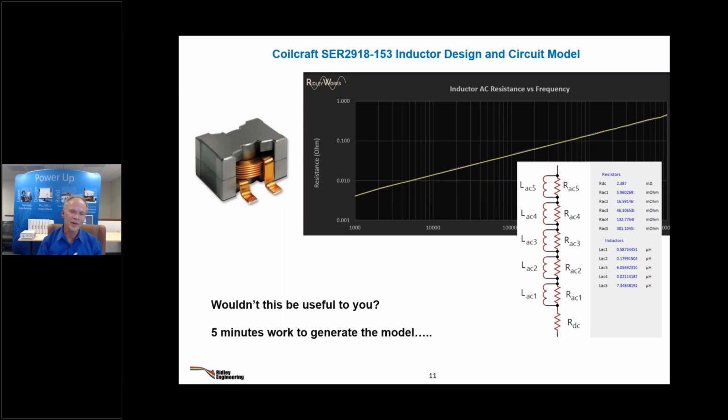So one thing that we're looking for: these models have been around for a long time. Even these circuit models have been around since 1993. Isn't it time that some of the vendors started giving us a good proximity loss model that we can run in LTspice? We don't really want to jump into another program and then derive the losses by looking at this chart and this chart and this chart. Just run LTspice like we do on a FET. LTspice as a circuit model gives us the losses. So this is possible, it's quick. I did this just during the course of this webinar.